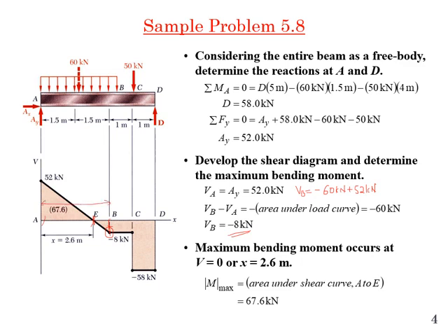The total is known, 3. So from E to B that will become 3 minus x, and this is x. So the location of E we can find is simply a similar triangle, that 52 by x should be equal to 8 by 3 minus x, and following this we can find the value of x, and it will be the maximum bending moment where the shear force will be 0.